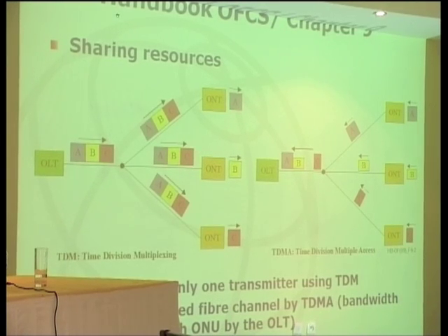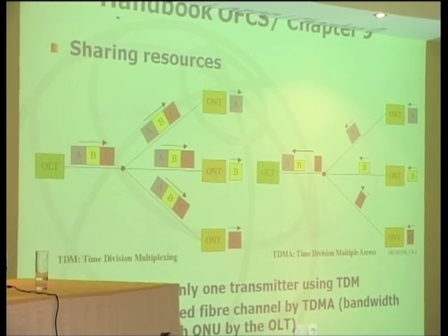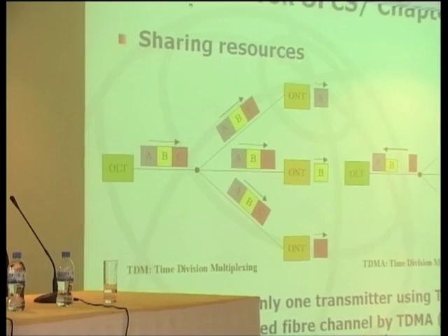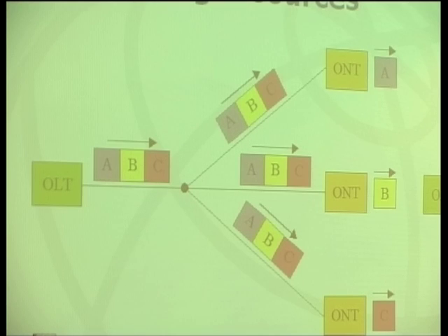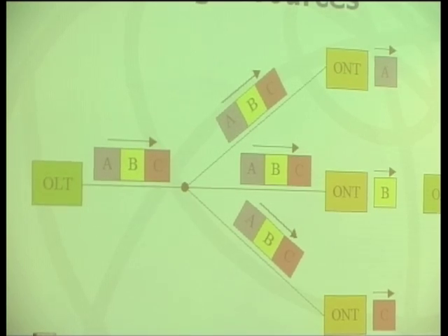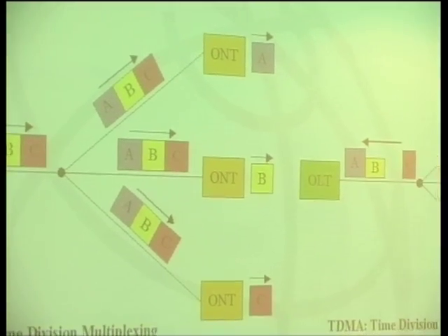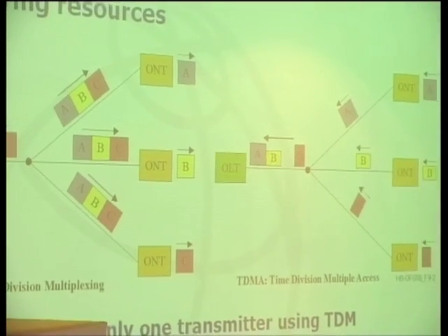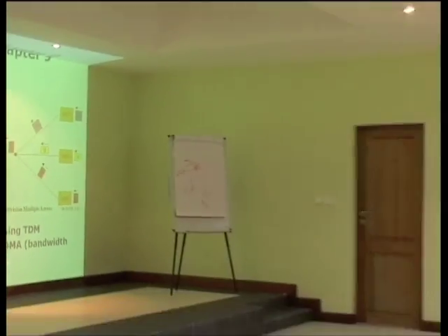Well, before starting again speaking about GPON, we have a splitter from the real world here, not from the paper, and you can have a look at it. It's a splitter with 32 outputs and 2 inputs, one working input and one protection input. Pay attention because it is very fragile.